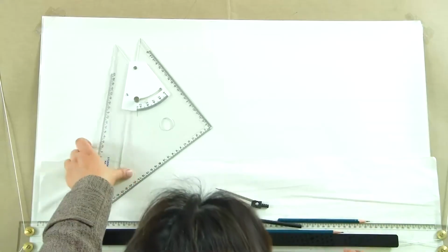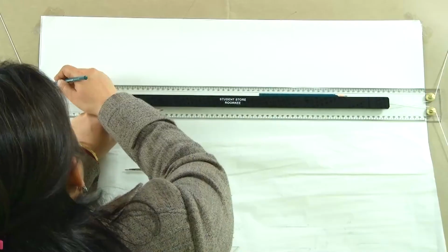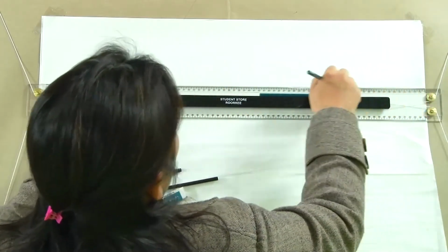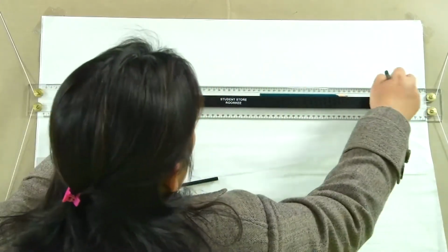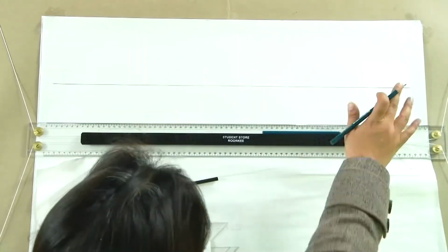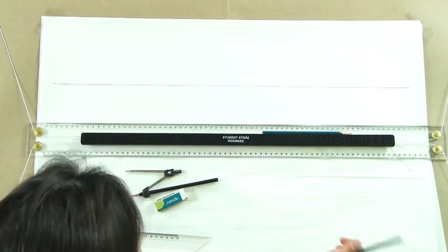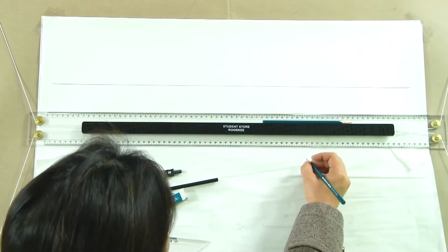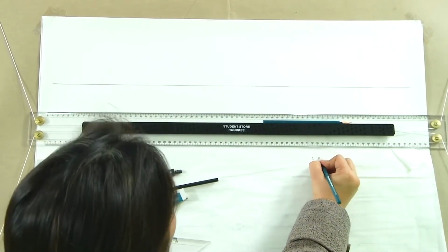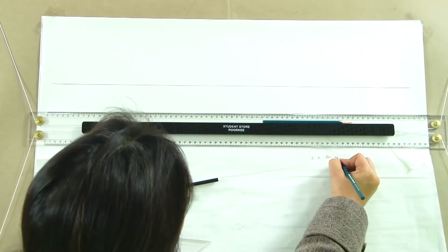So, let us see how to draw these various conditions for a line parallel to one plane and perpendicular to another plane on the sheet. Just like the previous case, let us draw a reference line, an XY line. This is the XY line that we are considering here. Now, let us write the conditions. So, there is a line of length 80 mm.